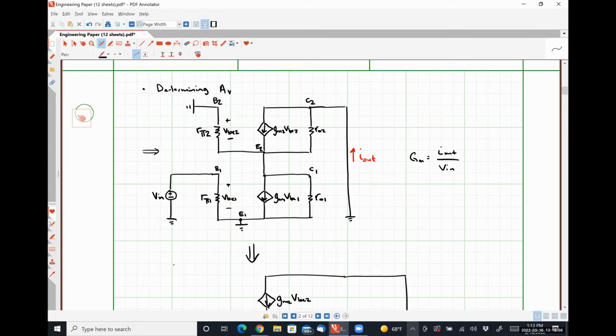100% agree. My argument there is simply because this resistor R02 is between this node emitter 2 and ground, we can lump it in here with this resistance as a parallel combination, and the splitting and recombining takes care of itself. I know that might be a hard pill to swallow, and I'm not sure that I disagree with you, but it's the way that makes the math easiest, which is the way I'm going to do it.